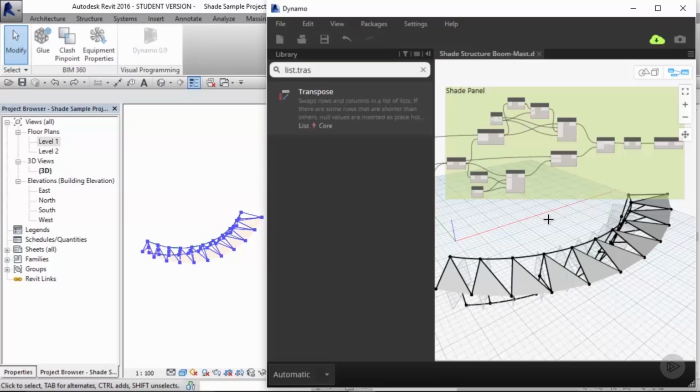In the next module, we'll briefly look at what it takes to make a geometry live in the Revit environment. With this being the course's primary modeling exercise, my suggestion to you would be to go back to the beginning, rebuild this definition, and try to change it slightly. A good exercise to go through would be to try and switch the direction of your panelization. You can also try panelizing a triangle in between your vertical masts.